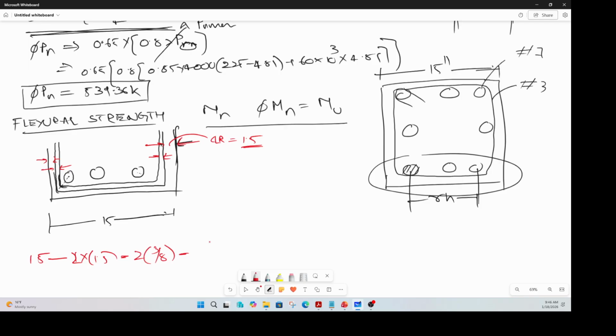And then you have to still come here. If there is a stirrup like that, the stirrup is not just doing a 90-degree turn like this. The stirrup is going like that. That means it has a certain radius, and that radius is based on the diameter of the stirrup.